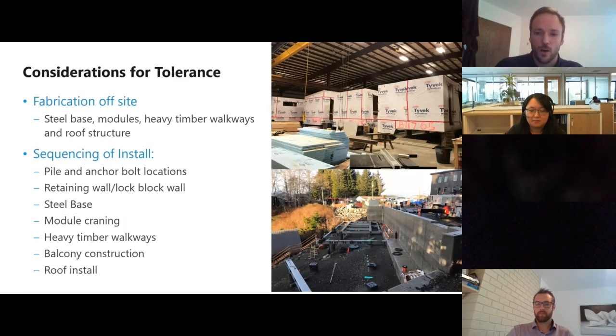Then the mods itself, we created a jig along the base of it. And so each mod that we set, we had to not only consider the X and Y plane, but we also had to consider the Z plane for the vertical, because the heavy timber had to be within 1/8 of an inch into, I believe it was the, I'll have to reference Esaly on that one, but I believe it was the floor joist that we had to anchor into. So that became quite a process.